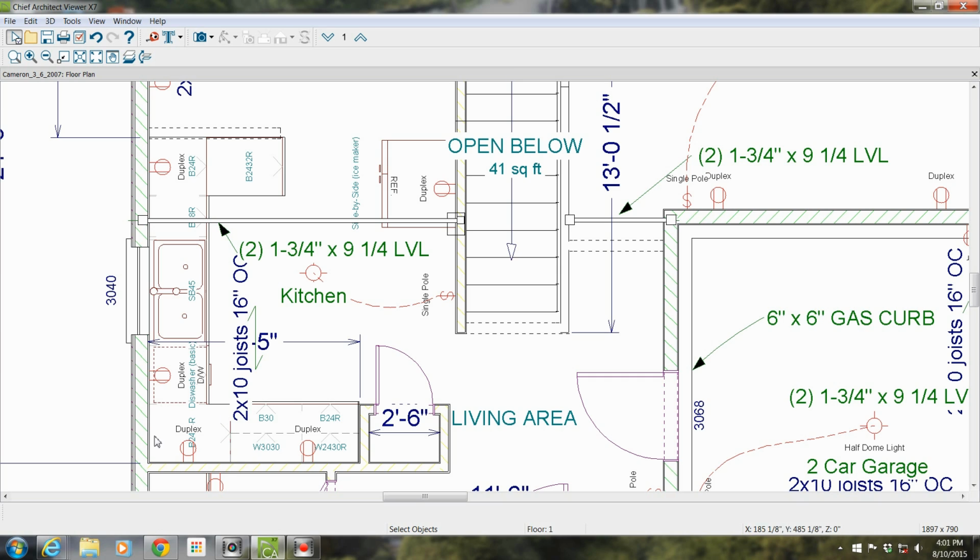You've got a dead space here. Up on top, you've got a base 24 here. Then you've got your dishwasher, and that's going to be 24 inches wide. Dishwashers are standard, 24 inches wide. Then you have a sink base here. And then you have another base here.